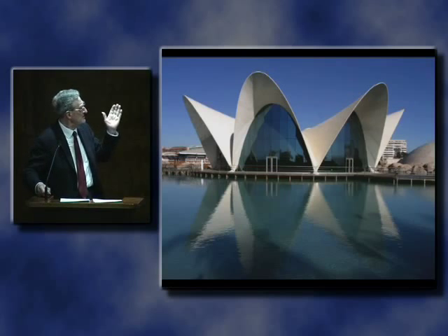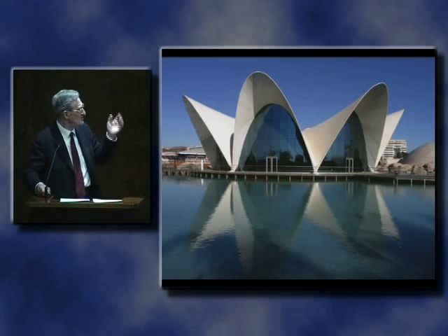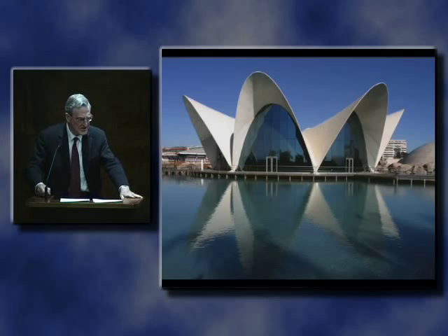And in addition, this cannot be a masonry vault. It is reinforced concrete with steel bars taking tension, and it's not possible to obtain solutions to our famous equation, not involving tension, and as you know, masonry is a material which is really unable to take tension. I must stress this again later on in a minute.